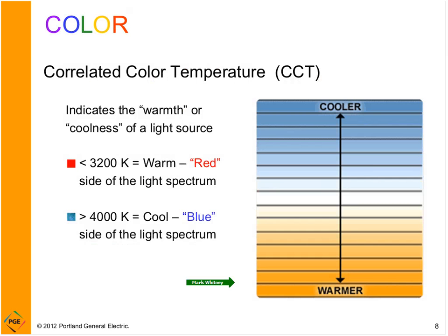However, most tasks can be seen better under cooler light sources, and that is because more blue in the spectrum helps make our pupils smaller, allows us to see more clearly. There are fewer aberrant rays, the rays that are not focused on that 2-degree view of vision on the fovea. Another important thing to know is that higher color temperature lamps may also allow for energy savings for certain applications, especially those that have a lot of detail and where acuity is important.